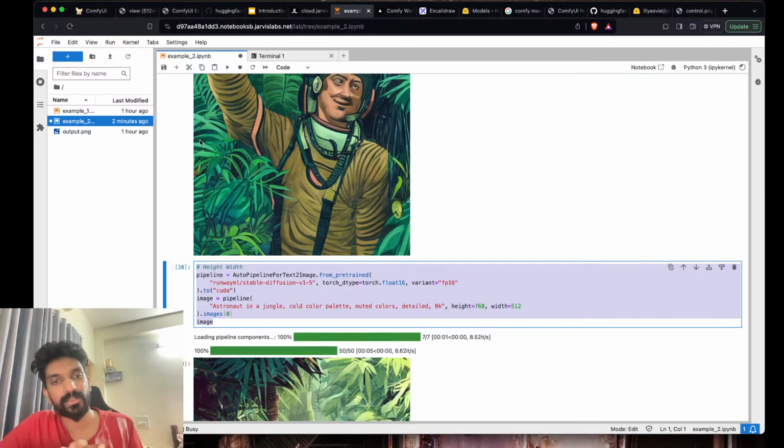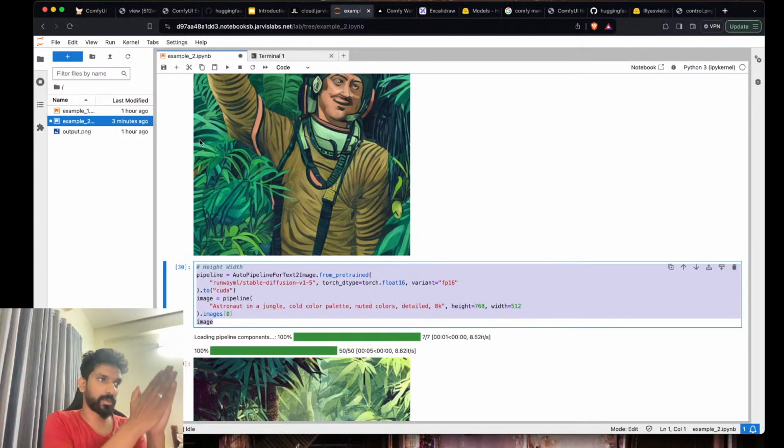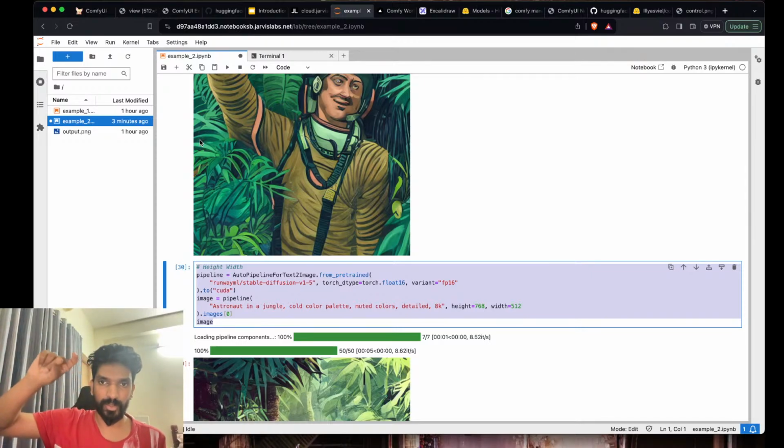You have to do something called a parameter sweep to figure out which parameters work for us, or how parameter A is affecting the output, right? So you can fix your seed, change different parameters, and then we do something called a design of experiments, and figure out what happens when I move parameter A to a certain area, whether it gives me a good output when I fix all the other parameters. This is how you figure out what parameters work for you, and then the combination of parameters that you want to work with, right?